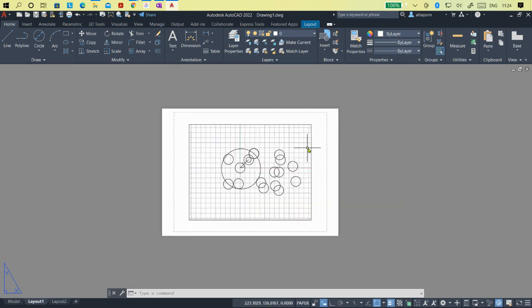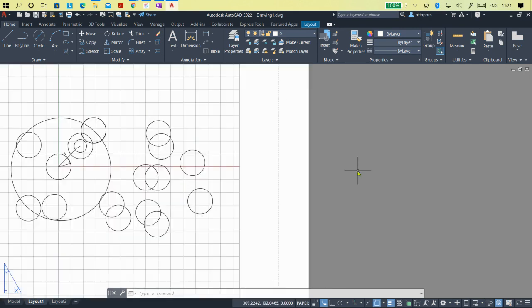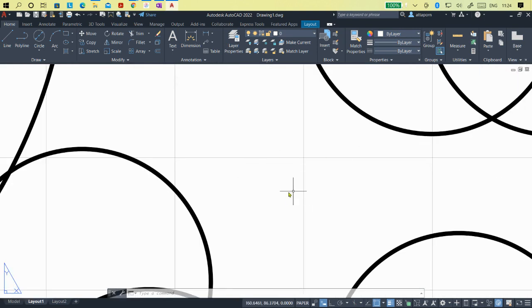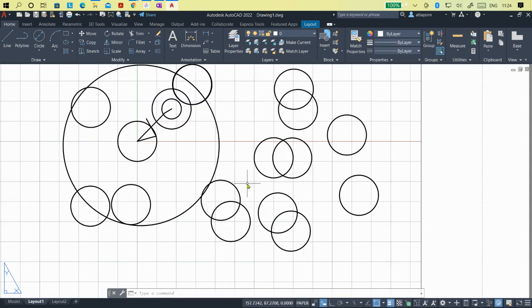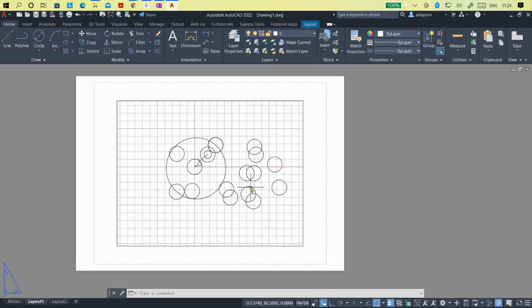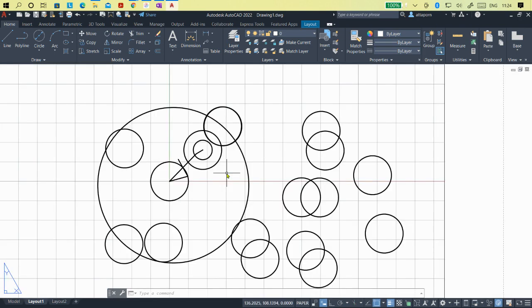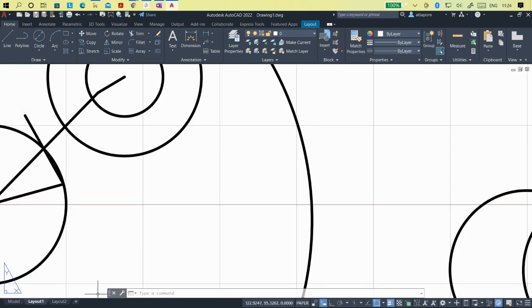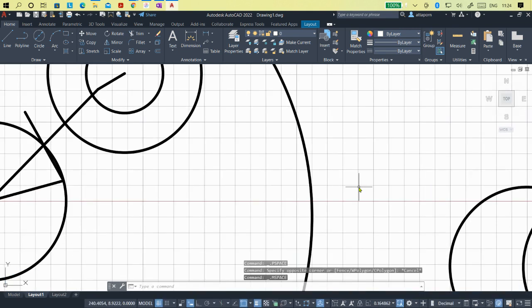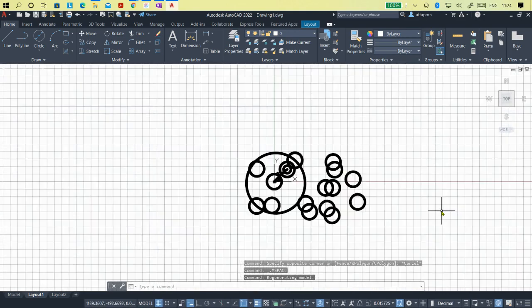But I want to warn you about something. If you zoom out the drawing paper like this, if you double click here, I don't want to show you. Maybe okay, I can show you. If you zoom in, zoom out before you double click, it's okay. You can come back to see the whole paper, but if you zoom in with no gray area, and you double click, you cannot go outside again.